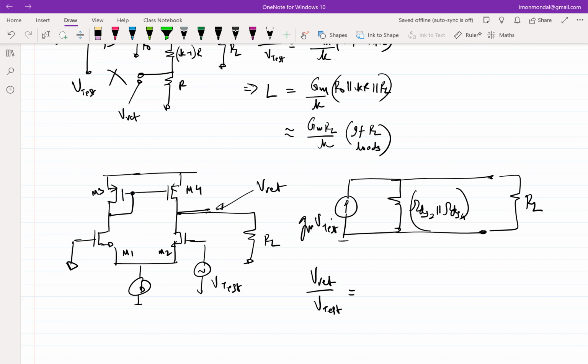No, right? In this case, no, because I have a mirroring from here. Half GM/2 comes from here, half GM/2 goes from there. Because of that, it becomes GM, right? Okay, so in this case, the sign will be negative because I have applied the input at the other terminal.